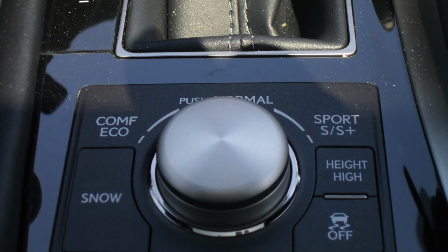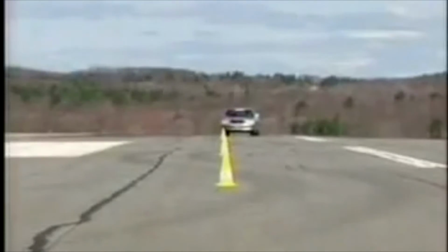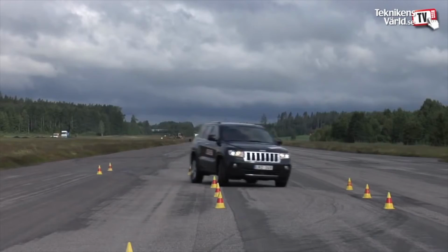The car's drive mode selector plays an important role in the operation of the P, I, and D terms of the controller. Looking at the luxury versus sport mode, the sport mode will have an increased proportional value, which affects the aggressiveness of the response. The mode selection will affect the ratio of P to D strength, with the sport mode favoring a stronger P to D ratio and the luxury mode favoring a stronger D to P ratio.